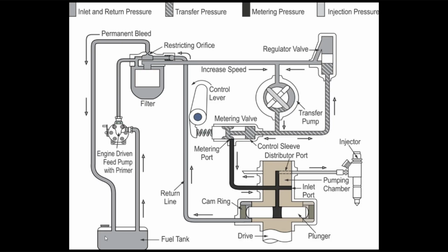The fuel tank is a reservoir that must hold sufficient fuel for continuous engine operation. From here, the tank allows returned fuel to settle and cool before being recycled through the system. Pressures in this tank are kept atmospheric, which is about 14.7 psi, for ease of withdrawal. From there, the fuel is sucked into the system via a lift pump.